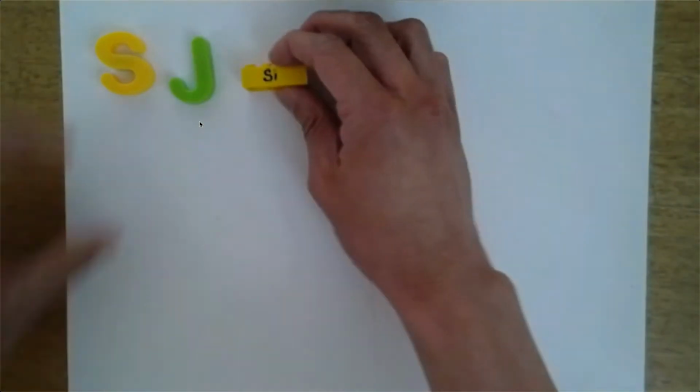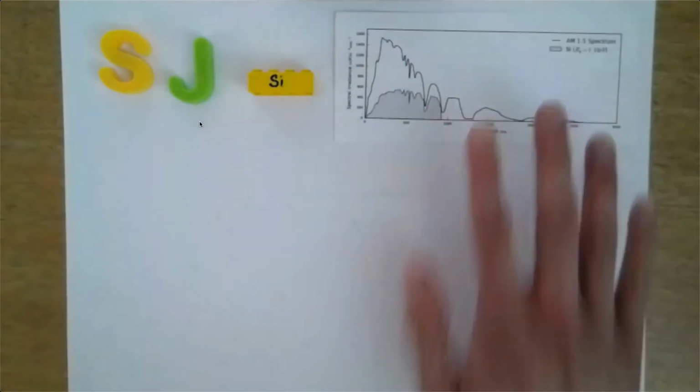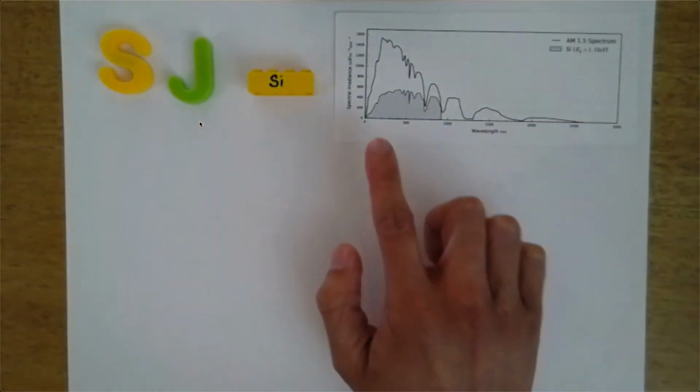Okay, so let's begin by talking about what is the state of the art in terms of solar technology these days. So obviously we see a lot of solar panels around, and most of these solar panels we see, in urban areas and rooftops, they're what we call single junction solar cells. And it's single because there's a single layer of semiconductor, typically that of silicon. And because there's only one layer, it usually has a relatively simple spectral response. So what's shown here is demonstrating that.